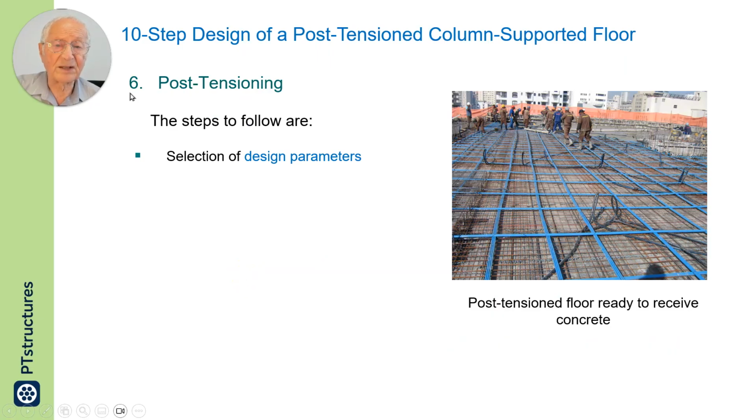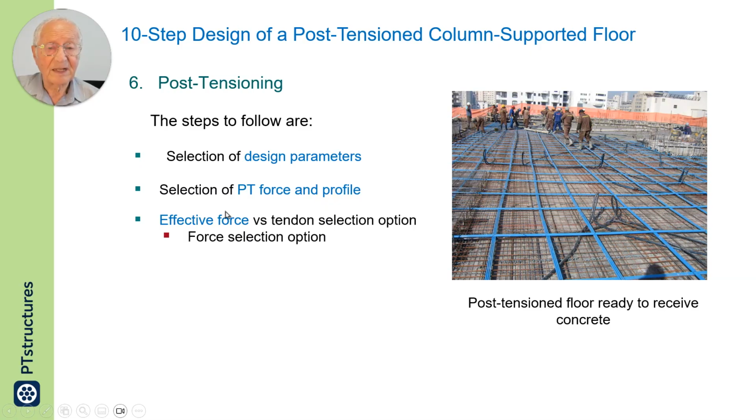Next, item 6, we move to post-tensioning. We have to select our design parameters. We select the force of post-tensioning and its profile, and we assume an effective long-term force that each strand will provide.